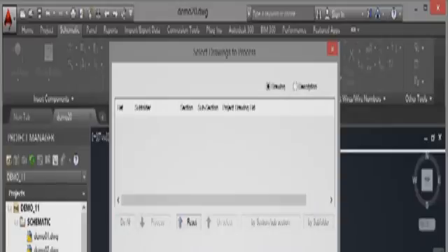Now, you would normally do something like that to allow for numbering, and also more importantly, it's a lot easier when you're on site installing these electrical installations, because you know that, for example, all of the 100s will be on drawing 1. Now, I don't know how many ladders there are in this particular project, but we'll find out when we do the renumber. So if I click on OK now, it'll give me the option to select all of the drawings in the project. So I'm going to click Do All.